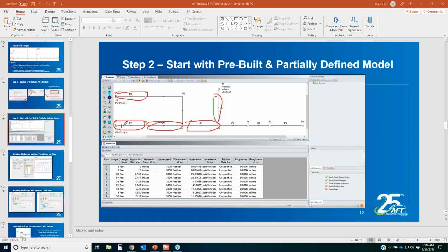Keep in mind that there are several more interior pipe stations in each of those pipes. In order to get a full picture, you will have to graph the excitation frequencies for all of the different pipes in your model, because you may have issues in other areas, and that's where you have to look at everything together. So right now, I'm only looking at a very small portion of the system in terms of the excitation frequencies there.